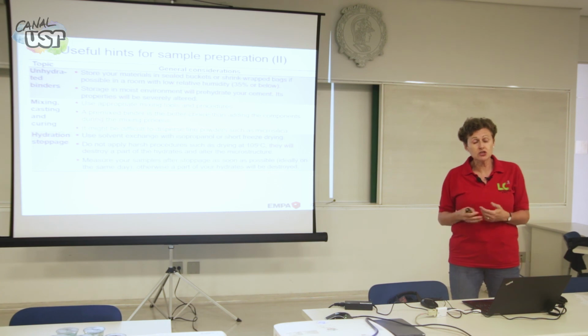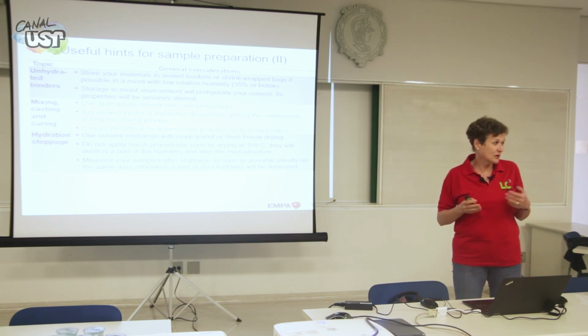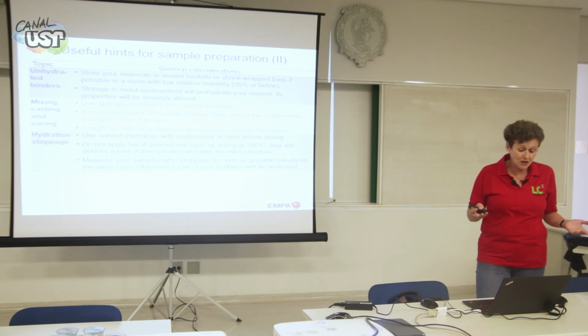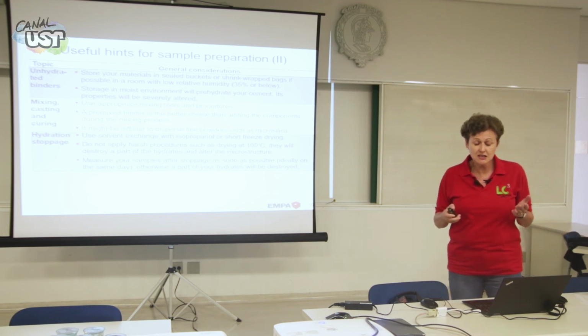But this value you get out of this is pretty meaningless in terms of real microstructure. It generally correlates quite well with the original water-cement ratio. So it has a kind of value for telling you whether you put a lot of water in your paste or not much water, but it doesn't really tell you what the real porosity is.